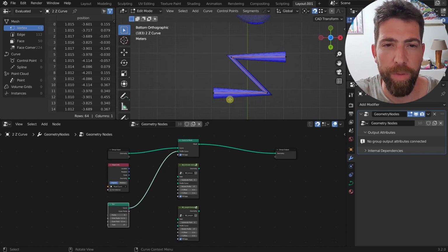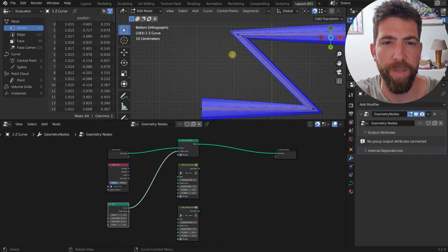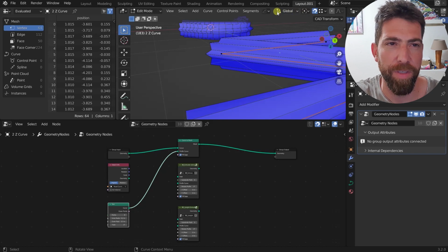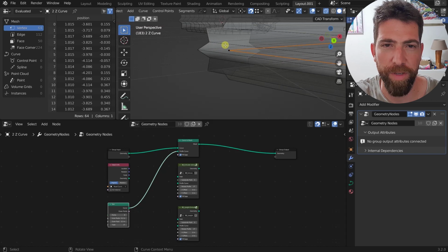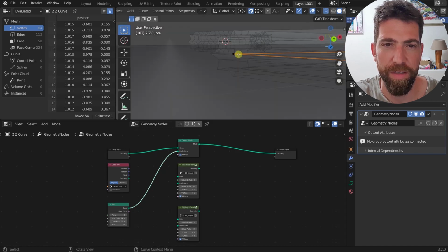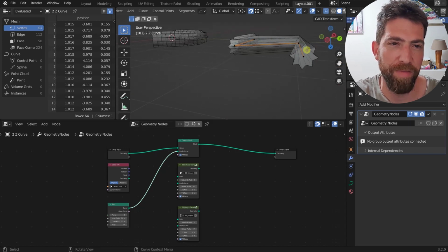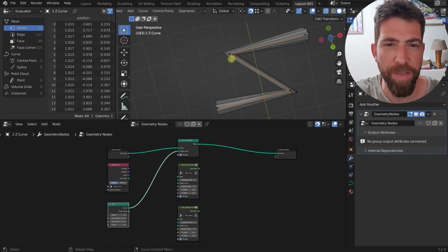And why is that? Well, because Blender here doesn't scale these profiles. If we look at it from this side, for example, and let me just turn on the see-through option, you can see this star is exactly the same in all the axes. So if we look at it straight ahead, it's just that identical shape, and it needs to be deformed because it cannot have the same shape here and also here, and that's because here we have